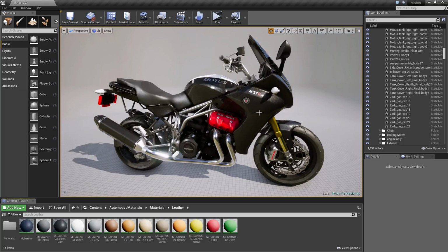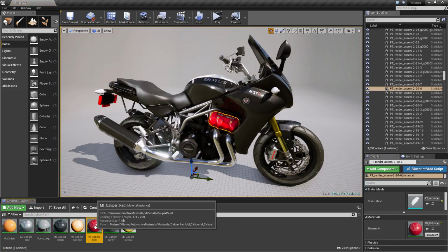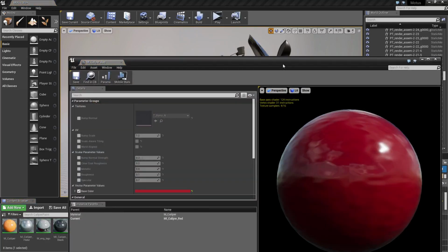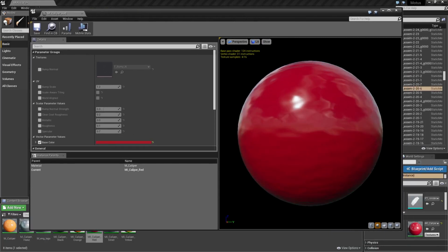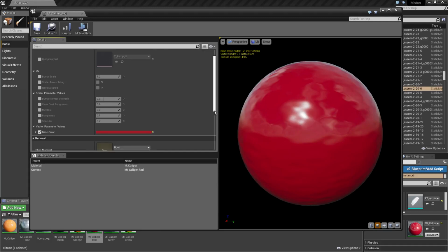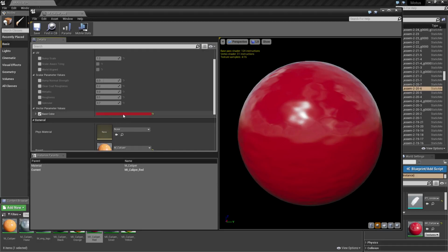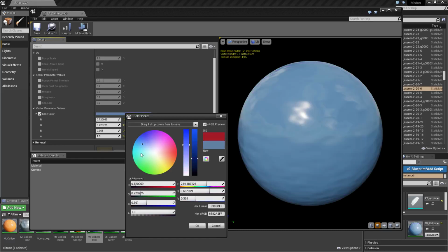So another thing here with the placement of materials, we talked briefly about this idea of utilizing the material editor here in Unreal. Well, what we can do very easily and very quickly in Unreal Engine is create something called a material instance. And what that allows you to do is create essentially something like a copy of a material, but it's a live copy in the sense that it doesn't affect the original, but there are attributes promoted from that original that you can affect.